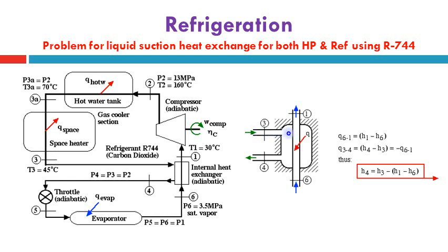So the gas enters this shell around the tube of the suction line, shown in blue, at state 3, is cooled, reducing its temperature, and continues its journey through the rest of the cycle at state 4.